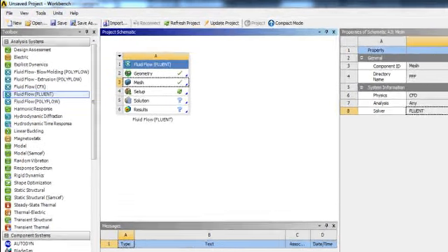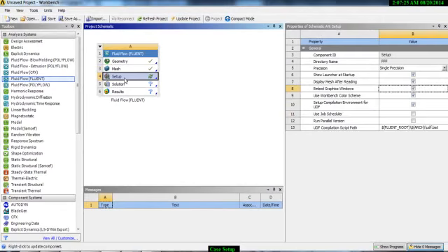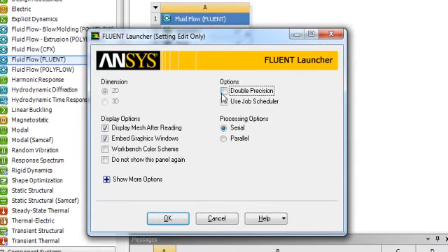So our mesh is done, and now we will go to the next step, that is the case setup. So go to case setup and your Fluent will open. Our simulation is right now 2D, and select OK.